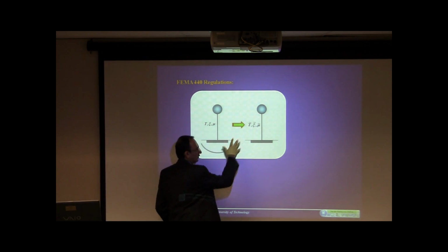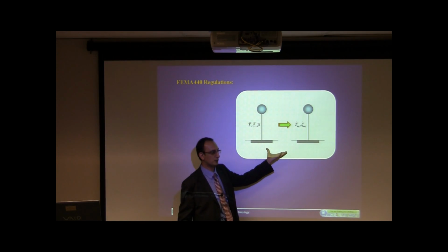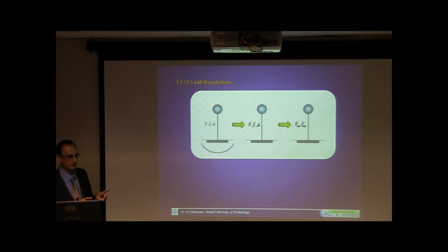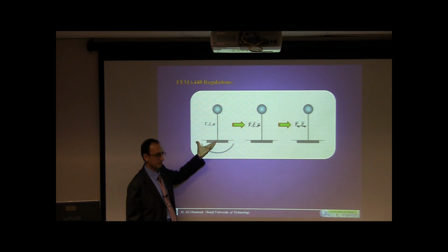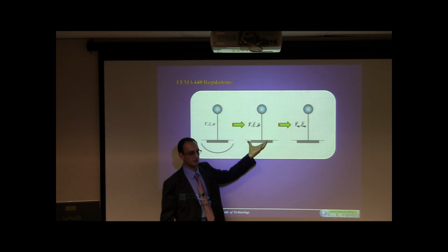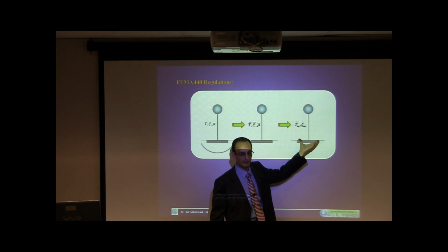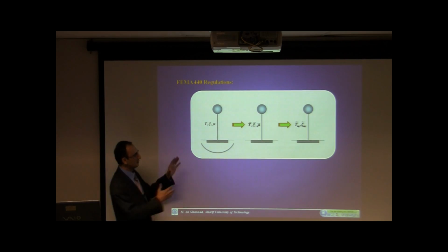And we know this problem, and suppose that we have solved this problem for the fixed base structures. FEMA mixed both of them, so it starts from here, making a fixed base structure with equivalent parameters, and after that changes it to the equivalent linear system with equivalent damping, and gets rid of this ductility. But it's a separate analysis.